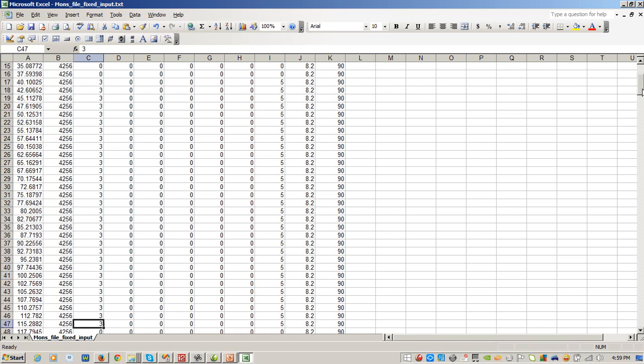However, here's the real trick for young players. What you've got to do here is also make sure you put in an estimation for lateral acceleration, in G. Now, this doesn't have to be 5,000% accurate. Quite to the contrary, because we're using this in a slightly different way. We want to overestimate what our G is going to be, because part of the safety in the track replay simulation is that if you've got a badly conditioned model, we use the lateral G as a measure to clip that, just in case the results start to go silly.